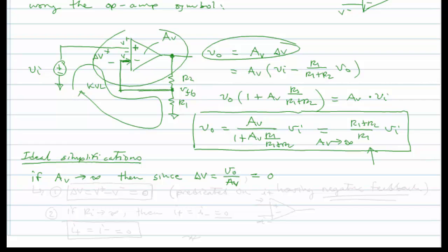That's possible if you had a high voltage op amp that was powered off of some power supply rails that exceeded 1,000 volts. Right? But most of the time in the lab, you're going to be powered off of 10 volts or 5 volts, 15 volts, 3 volts, something like that. And so you have to keep in mind that although this ideal analysis would predict a higher voltage, you're not going to be able to achieve a voltage that goes beyond the rails. In fact, a lot of times you can only get within some fraction of a volt or a volt away from the rails. Right?